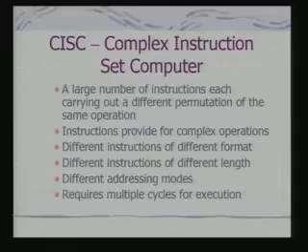So what we find is that the basic philosophy which goes into the CISC design is more complex operations being implemented in hardware and a more elaborate way of accessing data as part of the instruction set, because that's addressing modes. Addressing modes give you a variety of ways of accessing data in the memory, and you can even have operations involving data in the memory. These are the typical characteristics of a CISC processor.